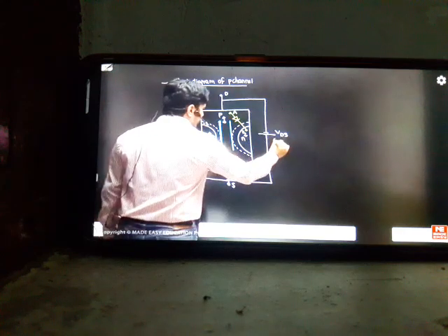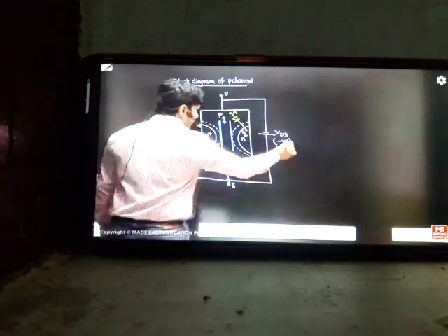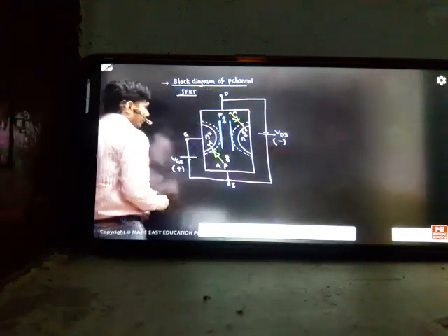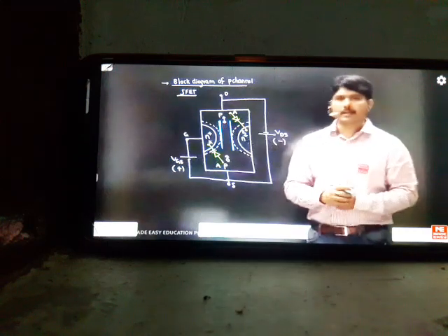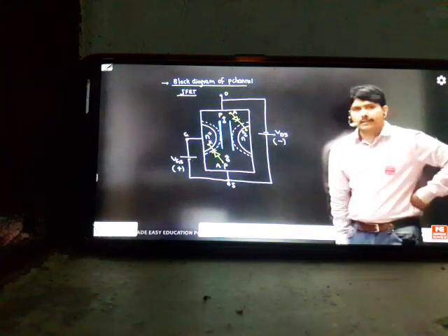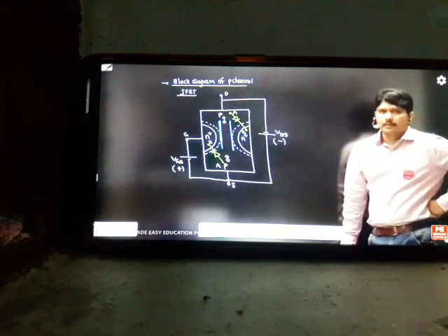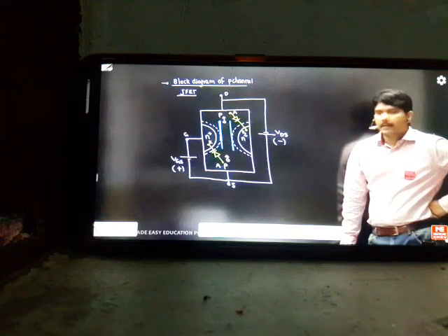In P channel, VDS is looking negative here. So like this, you have to remember the polarities of VDS and VGS according to the N channel or P channel. This will help a lot in analog electronics, the sign techniques. We're not changing the notations, we're changing the signs. The VGS becomes positive in P channel and VDS will become negative here.